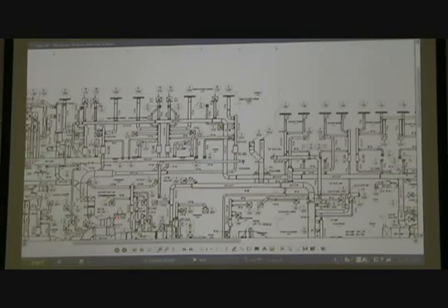Let's see the exhaust. Can't hardly see the floor plan. That's the exhaust right there. Picks up the toilet rooms here, toilet room there, toilet rooms in each patient room. That's considered low pressure duct. If it's connected to a fan, it could be part of an energy recovery unit, or you might be using air terminals on the exhaust even.